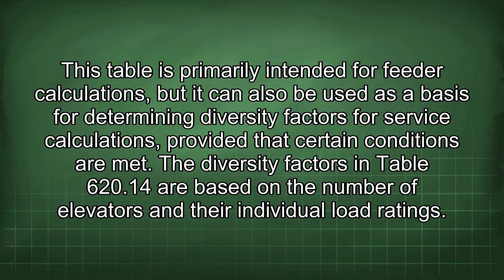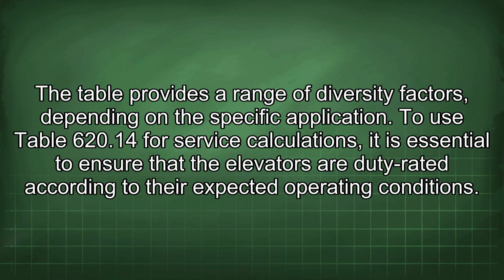This table is primarily intended for feeder calculations, but it can also be used as a basis for determining diversity factors for service calculations, provided that certain conditions are met. The diversity factors in Table 620.14 are based on the number of elevators and their individual load ratings. The table provides a range of diversity factors depending on the specific application.